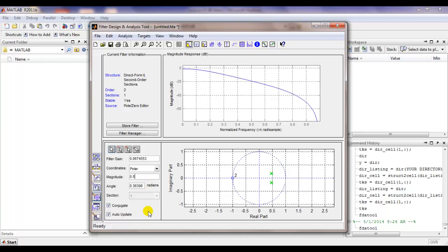start getting pulled down. Okay, so now when you have many poles and many zeros, they interact with each other according to the equation that I wrote, but the general principle stays the same: the farther away a zero is from the unit circle, the less effect it will have in terms of pulling the magnitude down.